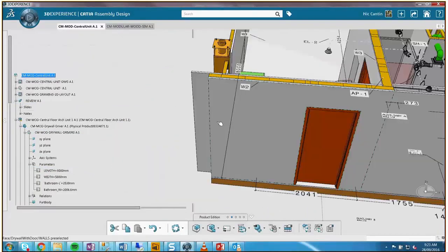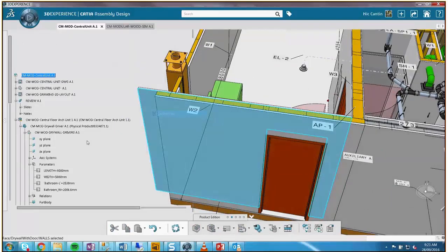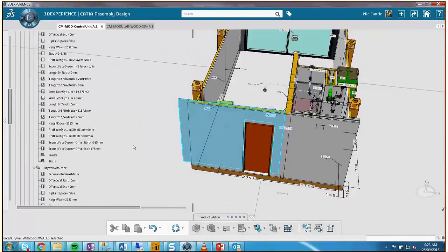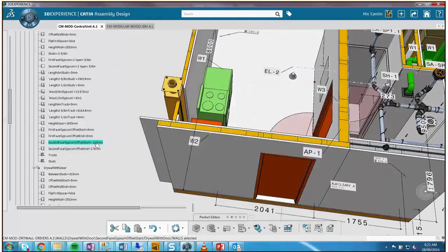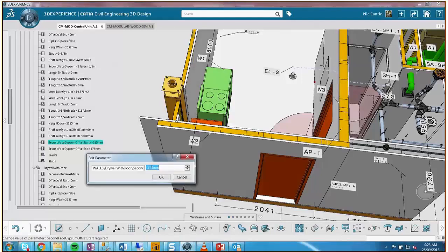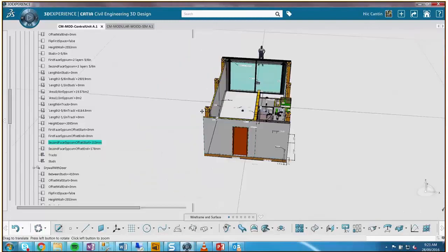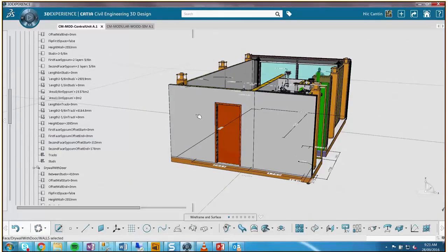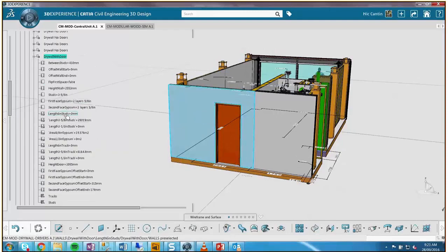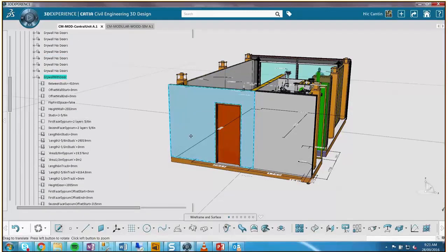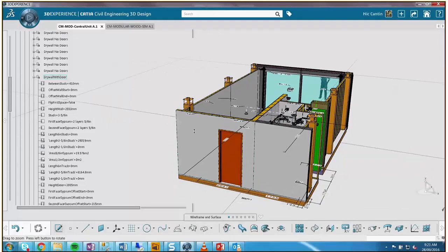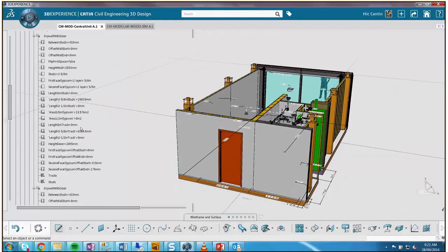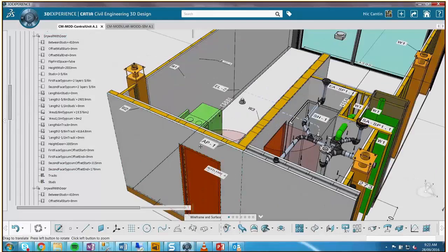As you can tell, there's kind of a few issues with the directionality of the line. Sometimes the direction of the line will move, and because of that, our offset of the gypsum there kind of messed up, so I have to reverse that. There are a few limitations with the tool, but overall, it's much better than actually modeling the wall itself or having just an extruded pad representation instead. So it's still a lot better in most cases.